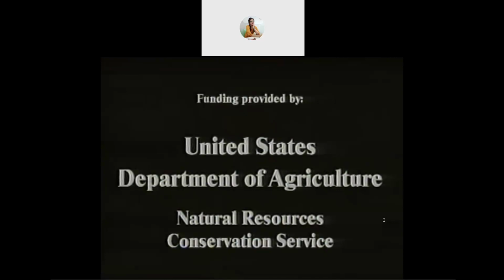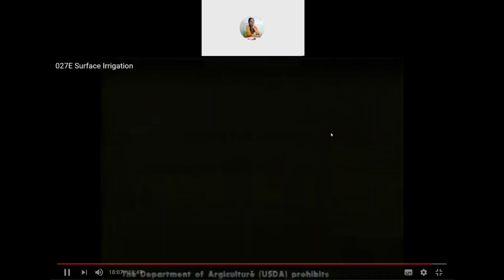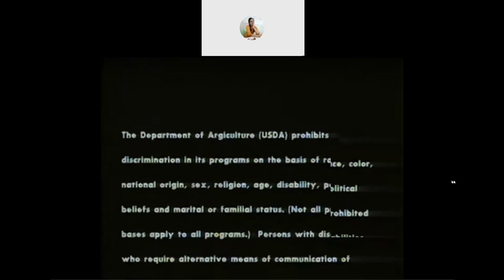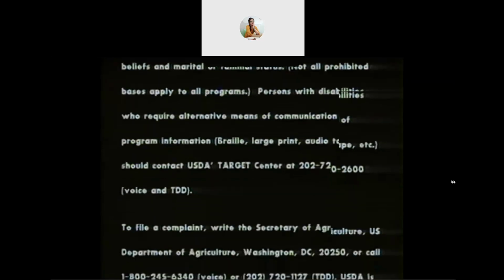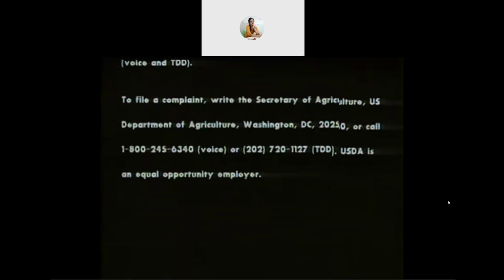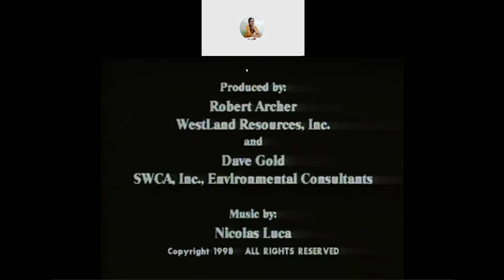Flow rate is the amount of water that is flowing in a ditch or furrow in some amount of time. For an irrigation canal or ditch, flow rate is usually measured in cubic feet per second, but may be referred to as CFS, feet, or feet of head. In some districts, the flow rate in the irrigation canal is given in miners' inches, or inches. Another flow rate to consider is the flow from the siphon tube into the furrow. This is usually measured in gallons per minute, or GPM.